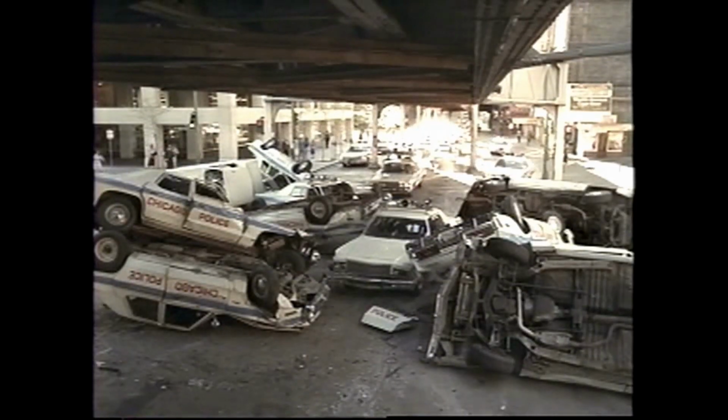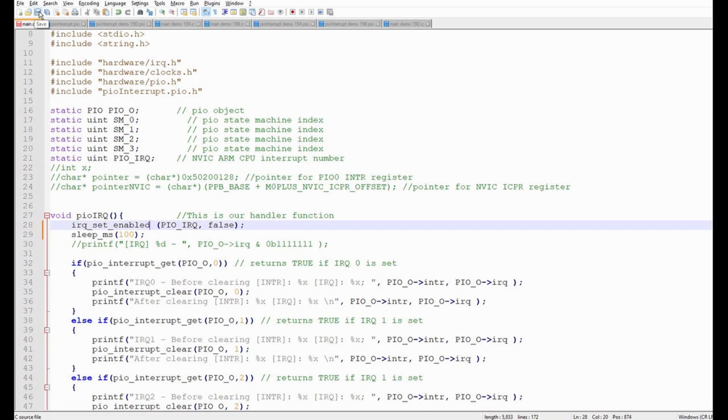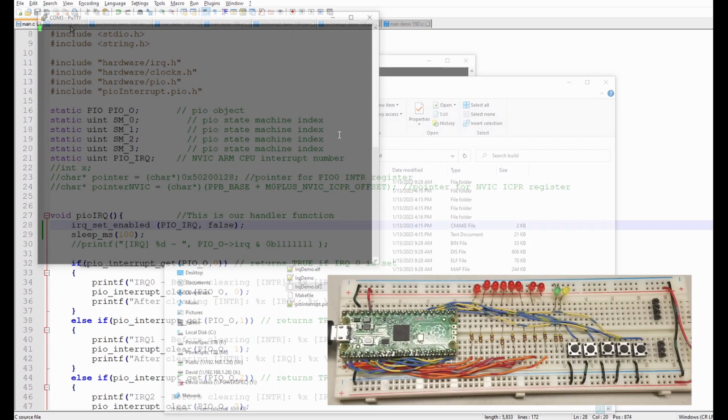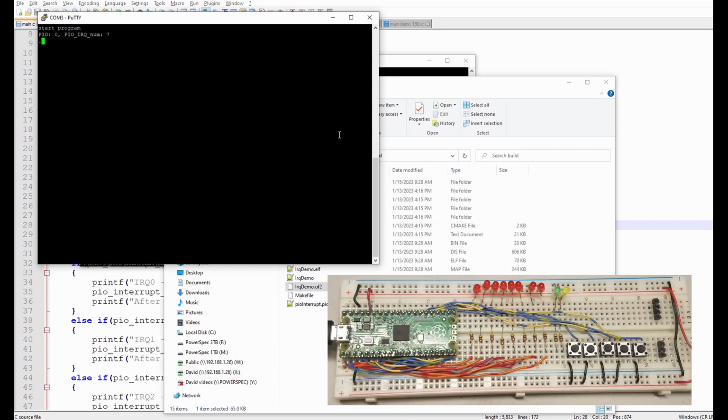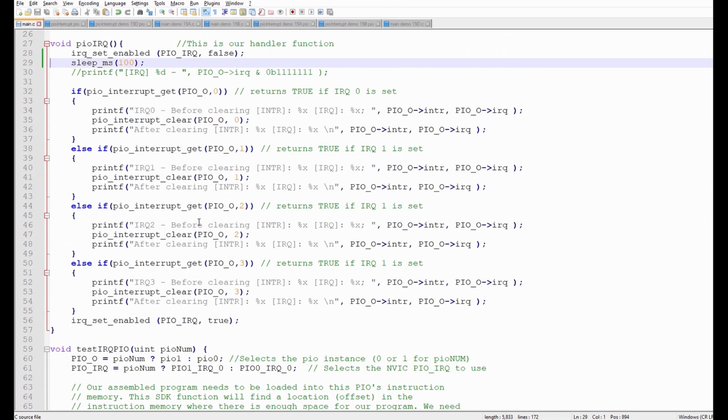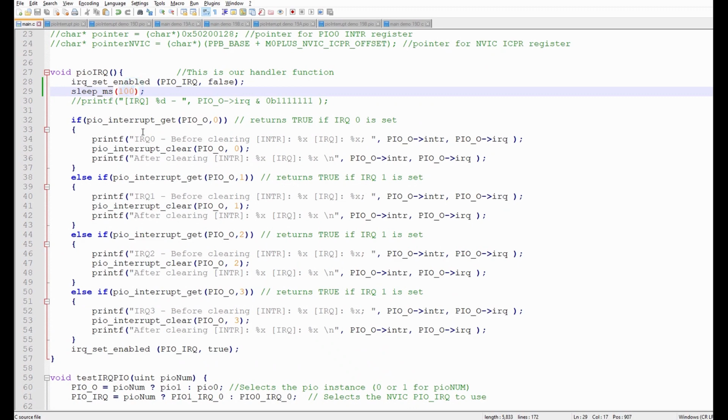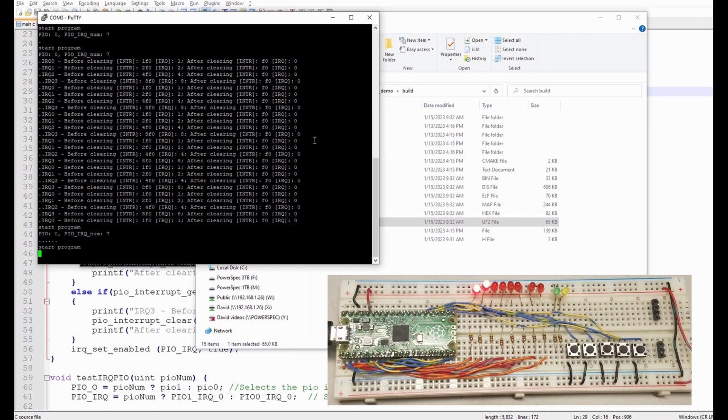It's very important that the callback routine be as short as possible. One thing I investigated for the last demonstration was to use a callback function which would stall until a switch was pressed. The Pico immediately crashed. So I tried seeing how much of a delay I could put into the callback function. It turns out not much. Here's demonstration 19C with a 20 millisecond pause. The Pico crashes. In fact, I shortened the pause to 1 millisecond and it still crashed.